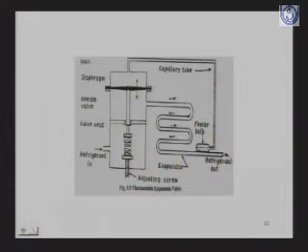And this is the refrigerant in from the condenser. So all the refrigerant will flow from the condenser, but the further flow to the evaporator is controlled through this expansion valve. You can see this is the valve seat, and this is the valve.